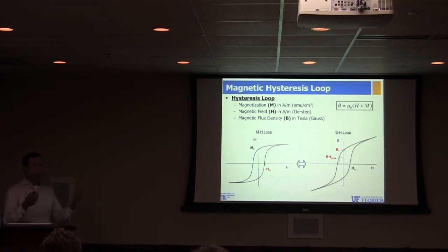It relates to how much energy the magnet can supply into a gap. Without going through all the details, it's the main figure of merit for quantifying the performance of different permanent magnet materials. What about squareness of the loop? Yeah, the squareness is important. I won't discuss that here, but that obviously will factor into the remnant value and the energy product as well.